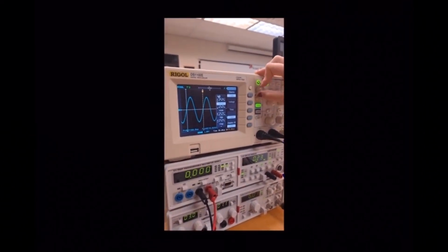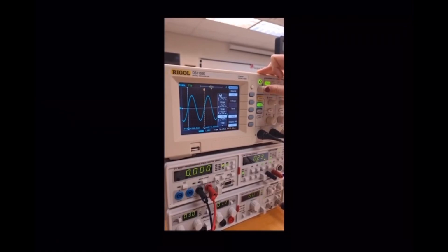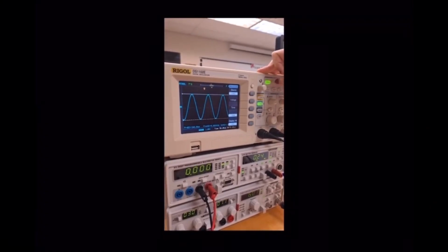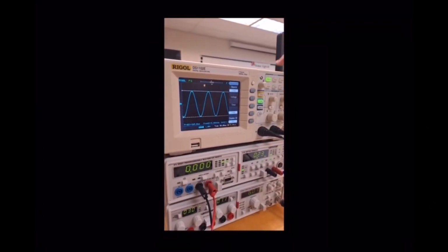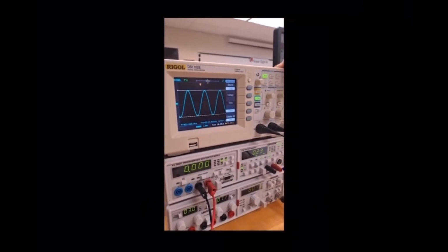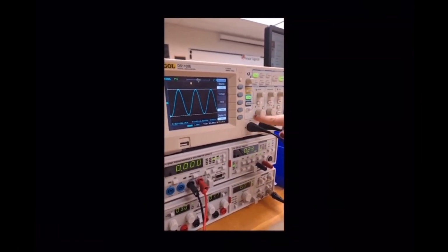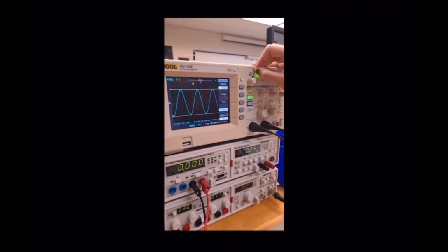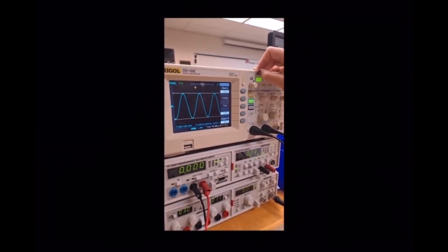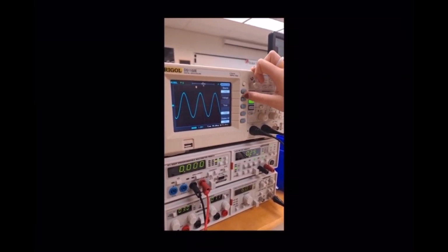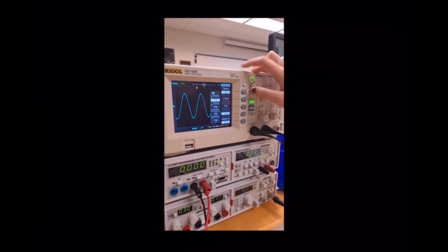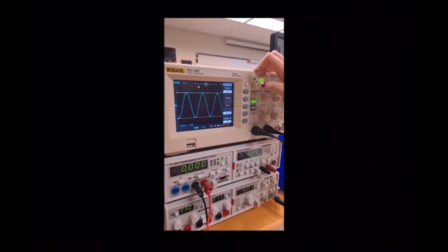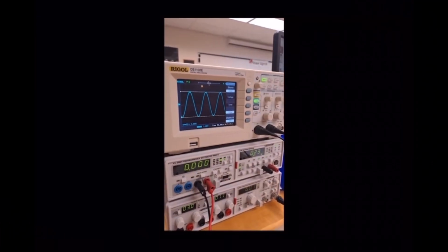Now we'll look at the voltage. So click voltage, then voltage peak to peak. Now there's quite a few measurements left at the bottom, so if you look where all the gray buttons are, you can see on our measurement menu that there's a button for clear, and you can just clear out the old measurements to make room for the new ones. And then we'll return to voltage and then scroll down to voltage peak to peak. And now we can actually see our measurement.